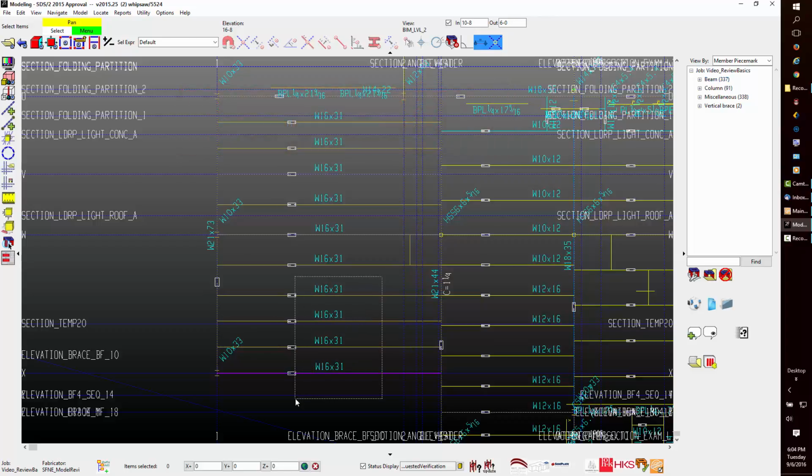When you press and drag your mouse from right to left in an area, you'll create a crossing indicated with a dotted line. This action will select any item that the dotted line crosses over. When you drag your mouse from left to right, this is an inclusive selection indicated by a solid line. The only items that are completely within the box will be selected. The option to add items by selecting Shift or remove items by selecting Control will function with this area selection.